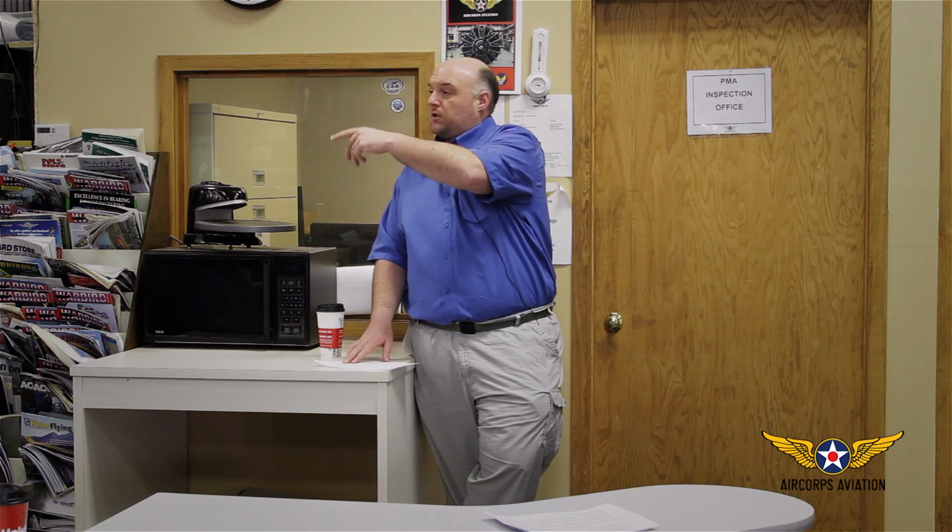It's going to be used for production. It's going to be over in a bin somewhere, but all approved material is going to have a -27 tag. Or it doesn't conform, and you're going to use a -22 hold material tag, which in our case right now is green. And that -22 tag is a signal to say, look, this doesn't conform to the specification on the purchase order. I ordered 2024 T3, I got 2024 O. Well, that's not what we need.